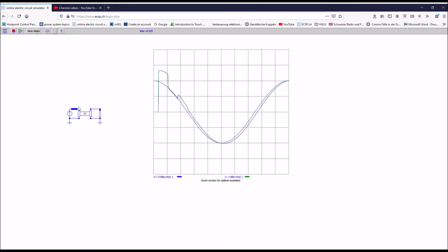When you adapt the number of steps, you also adapt the number of segments automatically. So I reduce the number of steps now to 500, and you will see you are now on 17 instead of 170 segments. These are the segments I have been showing before. So here you need to have at least 2 segments, otherwise the calculation doesn't work right.